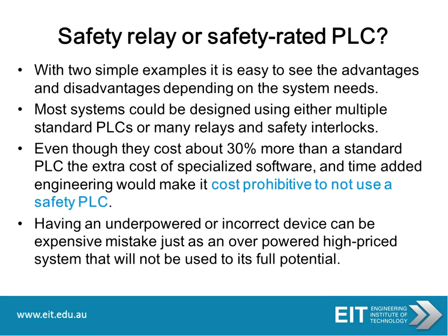So with these two simple examples, it's easy to see the advantages and disadvantages depending on the system needs. If it becomes more complex, we need a safety PLC. Most systems could be designed using either multiple standard PLCs or many relays and safety interlocks.